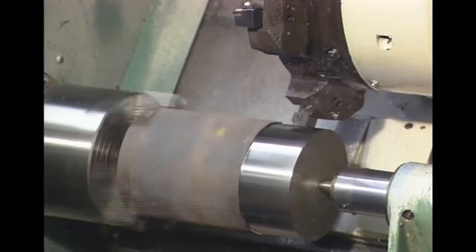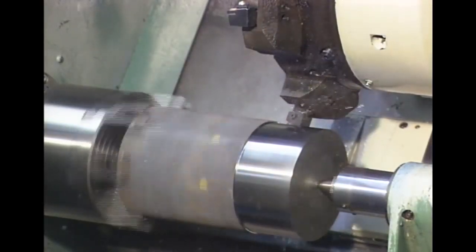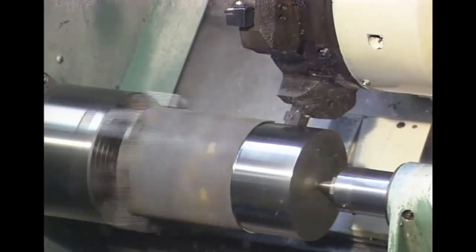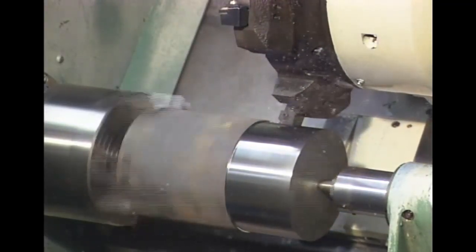Silicon nitride-based ceramics, also called sialons, offer greater toughness and thermal shock resistance than alumina-based ceramics. They are used in high-speed roughing applications and have excellent abrasion resistance. Silicon nitride-based ceramics are used for high-speed machining of gray cast iron, as well as on superalloys such as nickel and cobalt-based work materials.